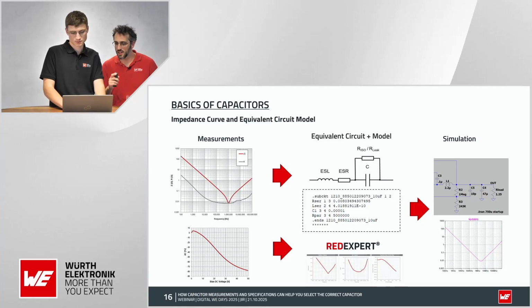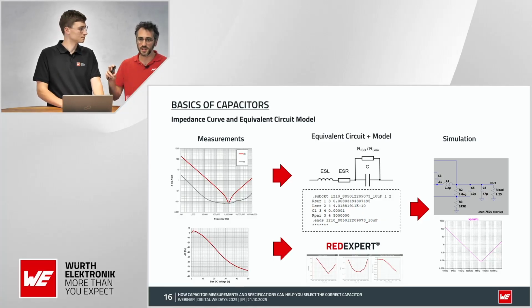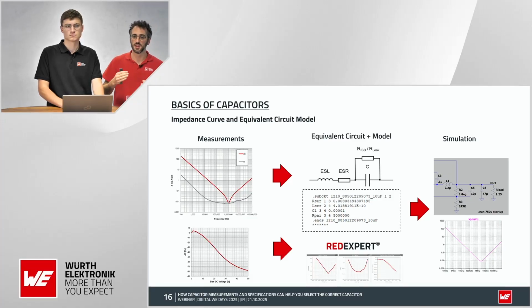Okay, then. Sorry, and also, can you reconfirm? Yes. All the effects, also DC bias aging, are completely reset when you do this preconditioning, this 150 degrees over 1 hour. This is what happens after Curie temperature, so the material is completely reset, the domains, the polarization.